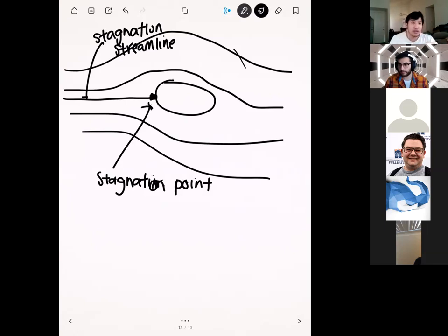And so another interpretation is that this is like a babbling brook, or a river, and you have a rock or a boulder that's in that river, and you have water that's hitting that boulder right there. So the pressure that develops on that boulder is due to the stagnation point. So basically anytime you have a solid object that's within a flow, there's always going to be a stagnation point, and there's always going to be a stagnation pressure on that flow. Okay. And the way that you compute that stagnation pressure is through Bernoulli. Okay.